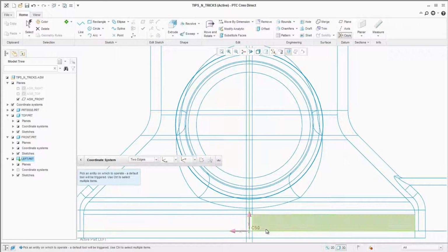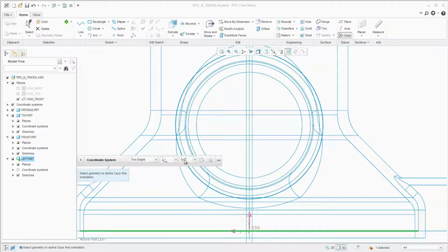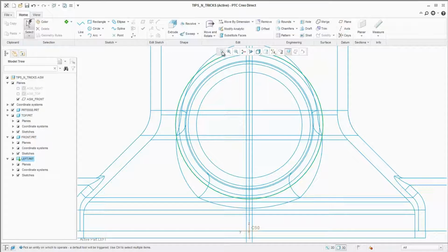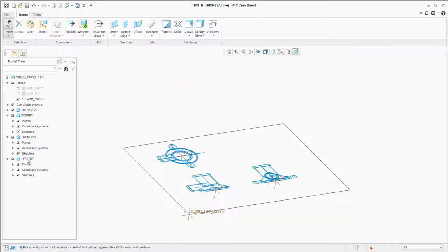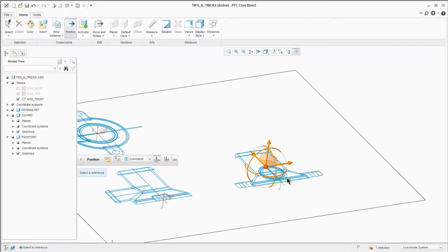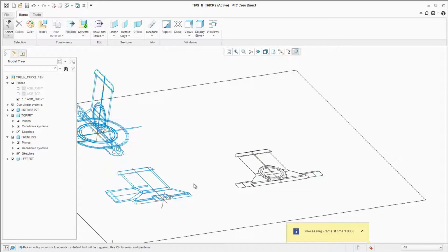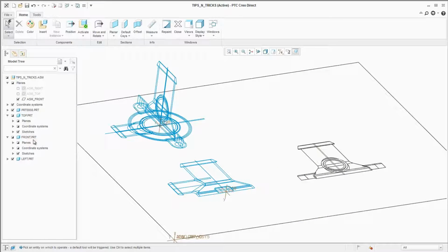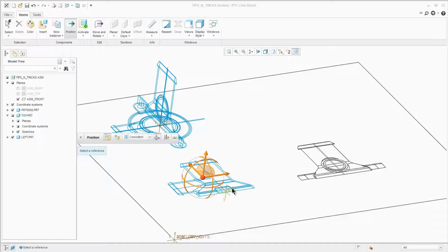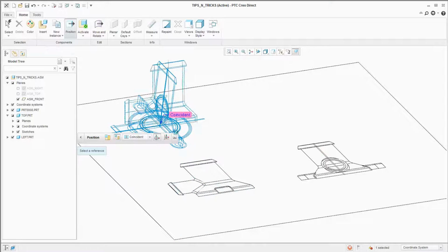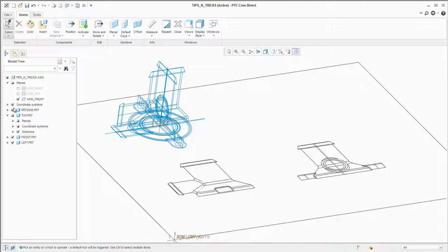Okay, again, this all now was just in preparation for us to get the view geometry separated into individual sketches to then orient them correctly relative to each other in 3D space, which is the step that we're going to do now. For this, we use the component position tool and tell it to orient the components so that the reference coordinate systems coincide. If we have defined them correctly, you see how the views now sit relative to each other in 3D, providing us already with a good insight how the model should finally look like and how to create it in 3D.